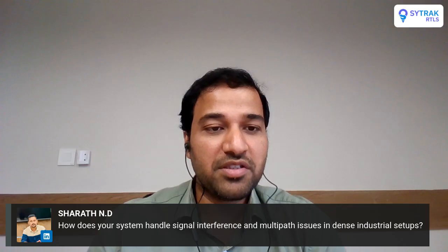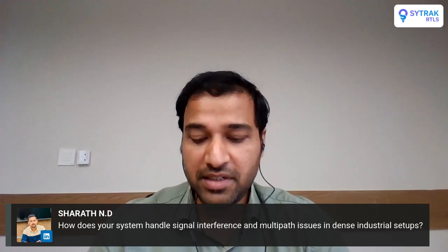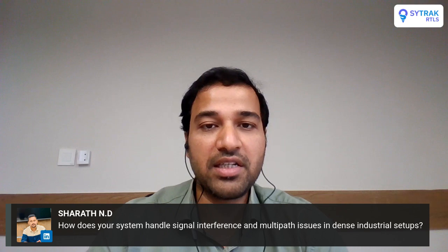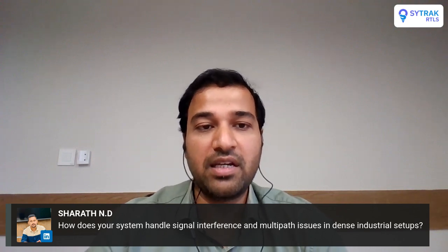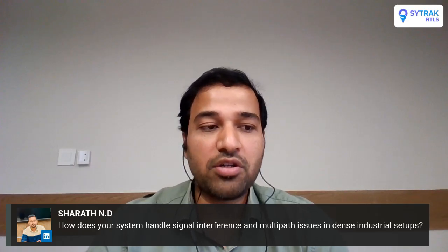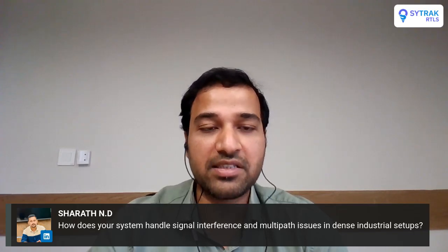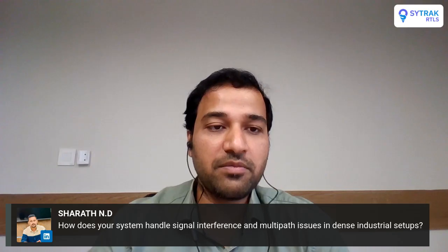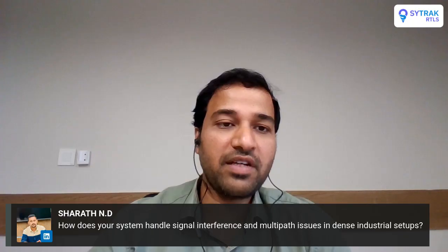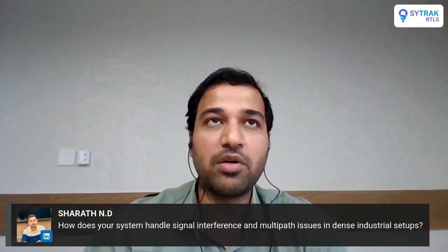Mr. Sharath, how does your system handle signal interference and multipath issues in dense industrial setups? So, like I said, this is a UWB RTLS tag, which has high resilience to multipath and dense industrial setups. Let's talk about an automobile setup a bit, which has a lot of equipment and a lot of metallic structures. Maybe there are racks available. Now, these anchors can have a ceiling mount as well as a wall mount. If ceiling mount is possible, where we are seeing a particular asset or the coverage area from a high mount,